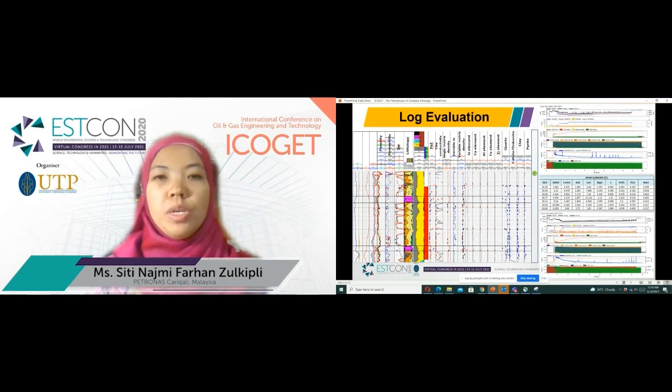Due to the complex minerals present and the formation tightness, identifying hydrocarbon presence in this type of rock is also difficult. Hence, it is highly recommended to deploy downhole fluid sampling and also downhole fluid characterization in order to determine the in-situ fluid properties such as the density, viscosity, GOR, bubble point pressure, the compressibility, and also hydrocarbon fluid composition.